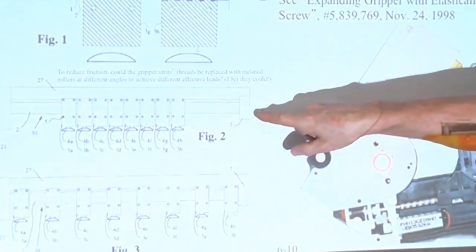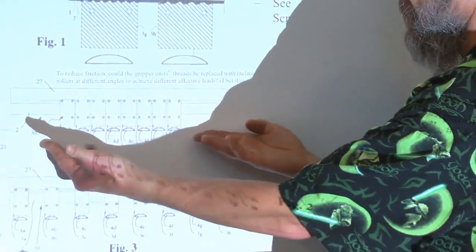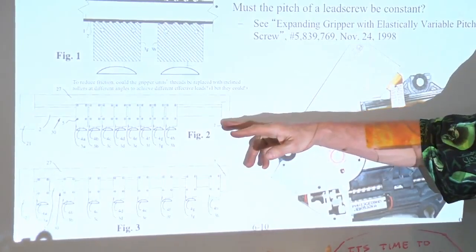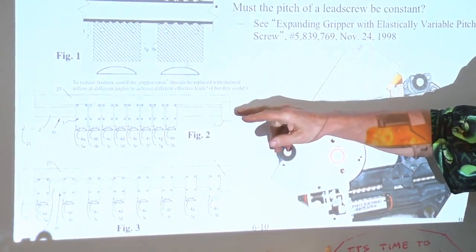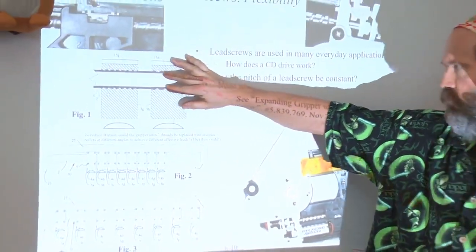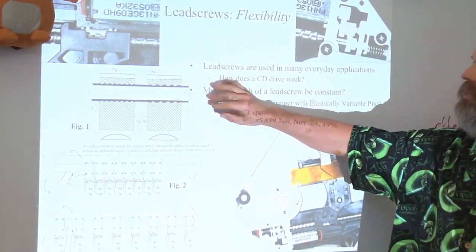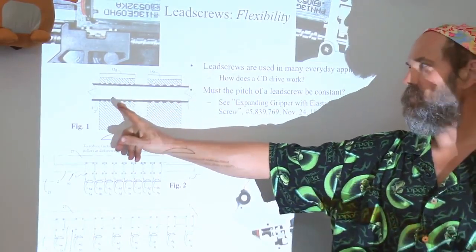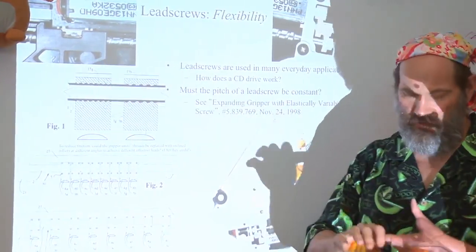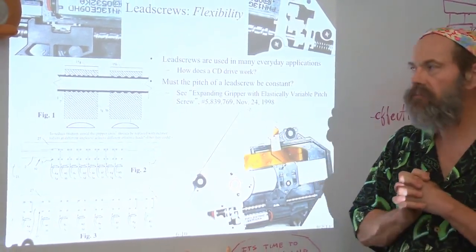This is actually from a device for picking up devices at one pitch and spreading them out to another pitch. Eggs, computer chips. This lead screw we had built worked really, really nicely. And it was based on using a smooth rubber shaft, or a shaft with a smooth, compliant rubber layer, and then each nut had a different lead. When the nut was engaging the rubber, it deformed the rubber and it made its own screw thread.